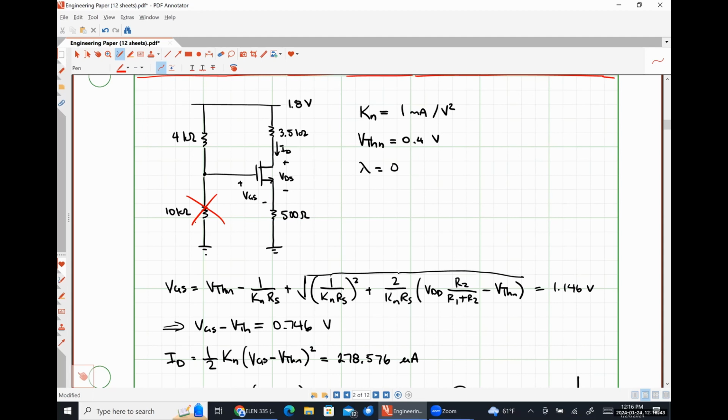Yeah, I mean, you can set one up like that. You can go get a MOSFET out of my office and burn one out, trying to set it up like that. It's just going to have a really, really large gate source voltage, whatever VDD is, and so it's going to try to push a whole lot of current through it. So probably wind up burning it out, but nothing physically stopping me from doing it, and see what happens.